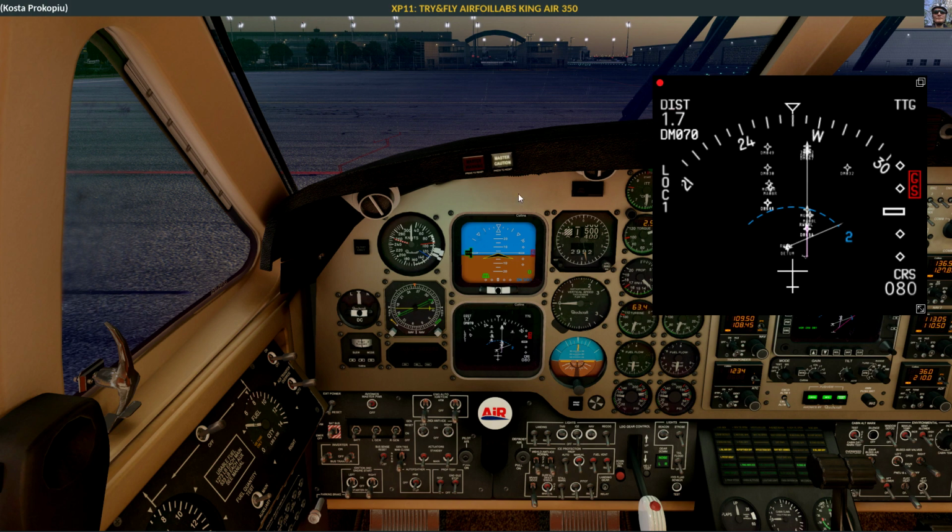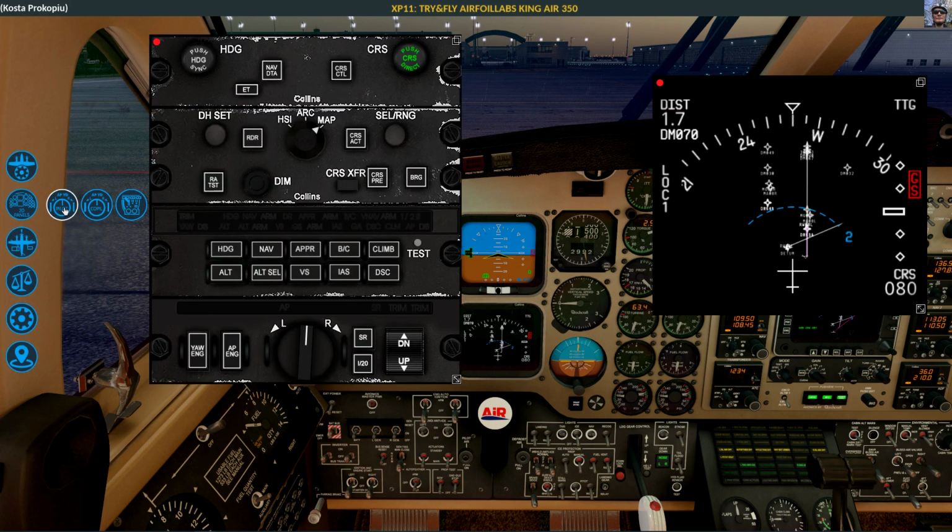Unfortunately, it doesn't show us any indication of the heading. Can we call this up as a 2D window? Hang on. Let's go to the autopilot 2D window and then have a look. So, nav data, TTG, GSP, estimated course. Okay, this is the course.